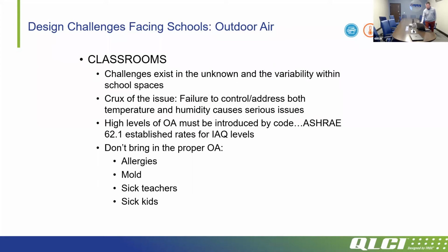At the crux of these designs is that they're densely populated spaces. In order to address that, we need to bring in the right amount of outside air at the right level, because if we don't, we start dealing with issues like how do we remove contaminants, or do we bring in allergies, mold, and ultimately sick kids and sick buildings.